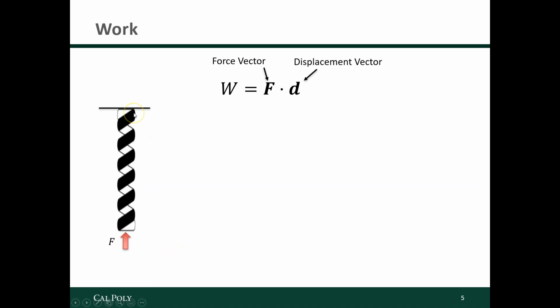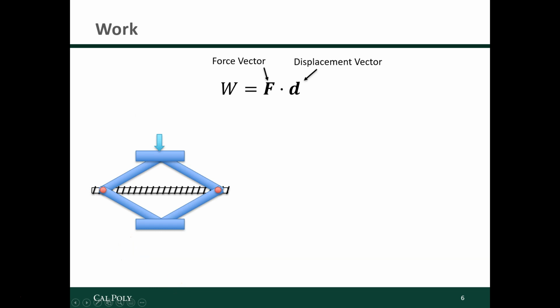So it turns out that the spring is stronger than our power screw in this case, or the power screw is allowing the spring to expand. When it does that, the force that the power screw is applying to the spring is apparently less than what the spring is applying, and so the spring expands and the force is in the direction that's opposite the displacement vector. So in this case, the red force is doing negative work and the spring does positive work on the red force.